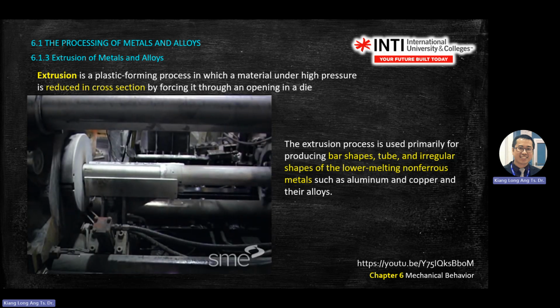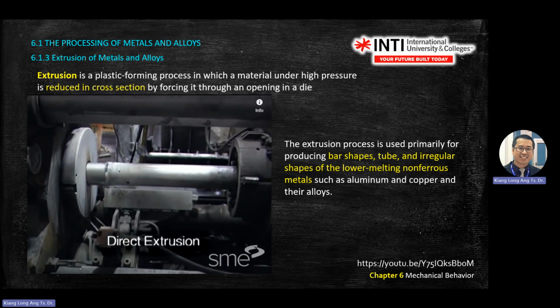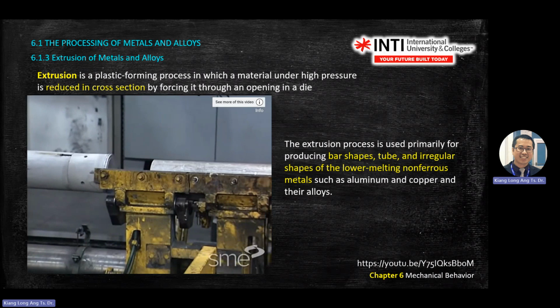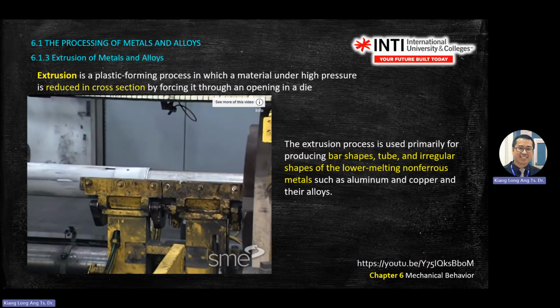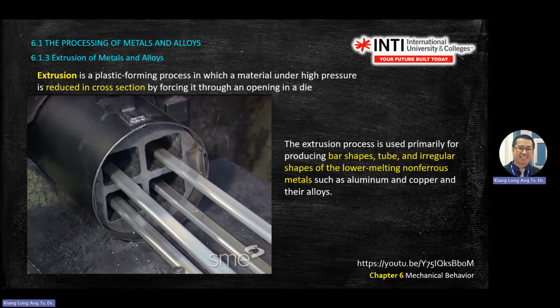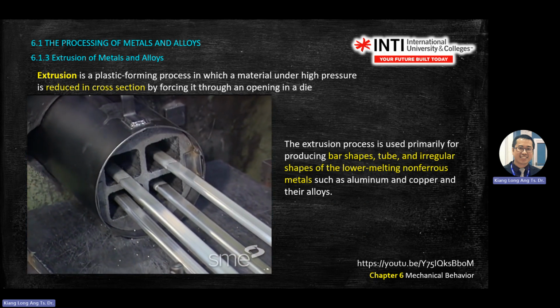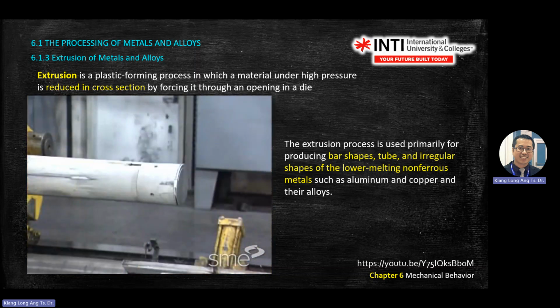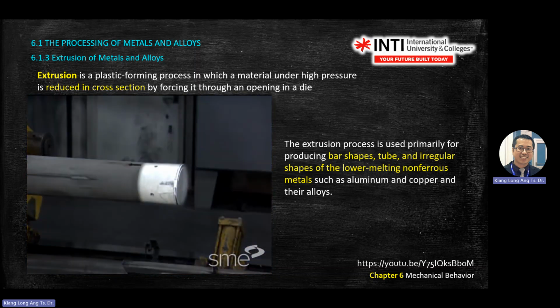The primary type of hot extrusion is direct or forward extrusion. The cylindrical ingot, the hot billet, is loaded into a thick wall container and forced through an extrusion die secured in a holder. The force for extruding is applied by a ram, along with an intermediate reusable dummy block.